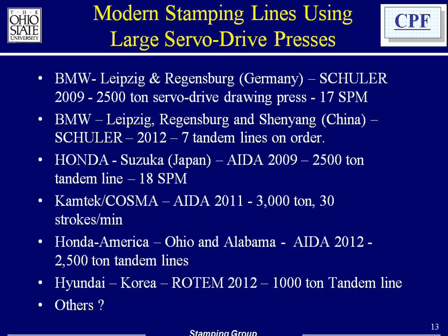To give you an idea about what is happening around the world, by the way, I should add at this point that there are really three, in my view, as somebody who's working with sheet metal R&D, three major developments going on in sheet metal forming technology. One is advances in advanced high-strength steels to save weight and improve crash resistance, of course. Number two, the technology that's called hot stamping. You may have heard about it, where a certain alloy steel is hot formed and then quenched in the die, and you can obtain very high strengths up to 1500 megapascal.